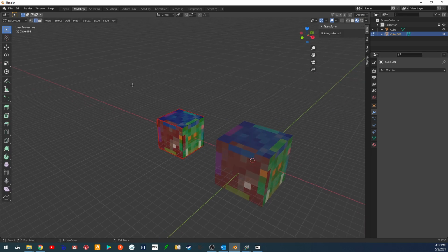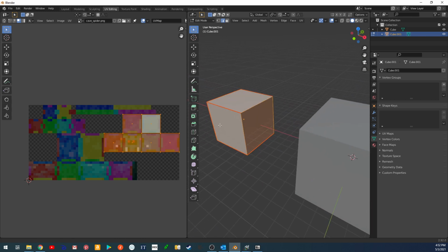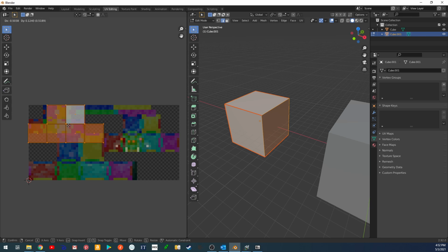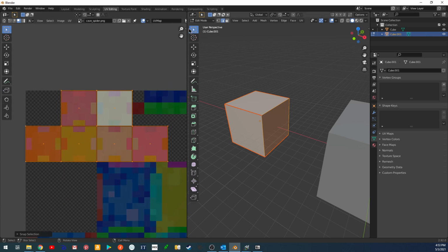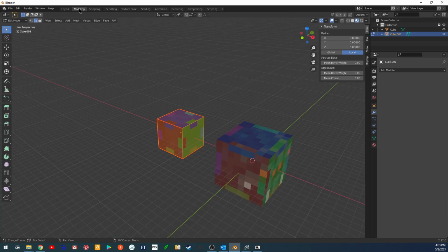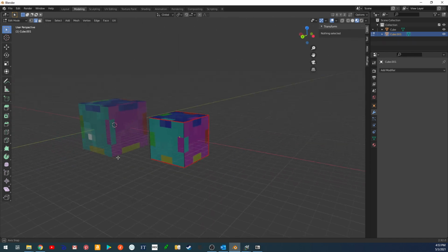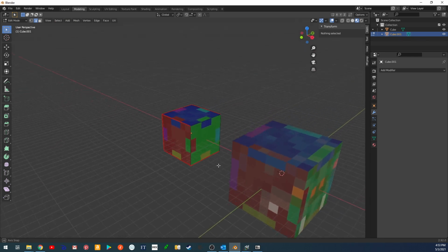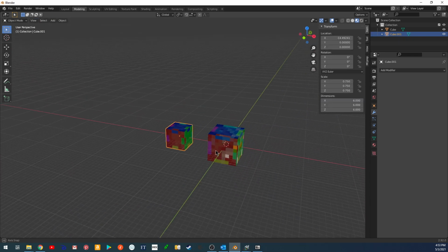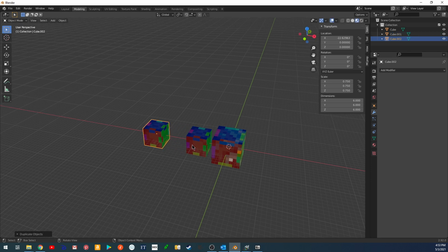Now we'll go to edit it. We'll go to the UV editing. We'll select all the mesh, and we'll just move it over here and scale it. And then we'll do snap to pixels. Looks good. Go back to modeling, and that looks good. And yeah, these colors just make it so much easier because you don't have any guesswork while you're working. So now Shift D again. Now for the abdomen,